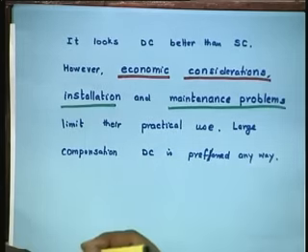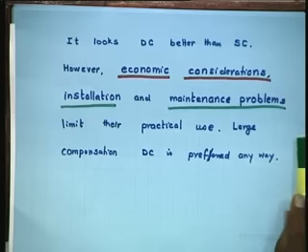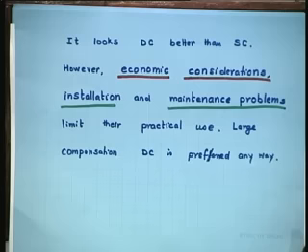If something is static, where is the question of maintenance? Why does a transformer have 99% efficiency? Because it is a static device. That is a standard answer to this question, which might have been put to you by several teachers in viva or selection committees. So, straight away there is no friction loss, there is no rotational loss and so on.